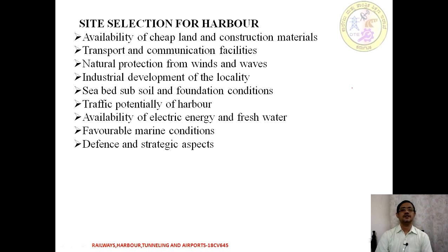Moving on to the first thing, that is site selection for a harbour. A few points have to be kept in mind when we select a site for a harbour. First is the availability of land, which should be cheaper, and all the construction material should be available. Next is the transport and communication facilities. Apart from that, natural protection from the wind and the waves.